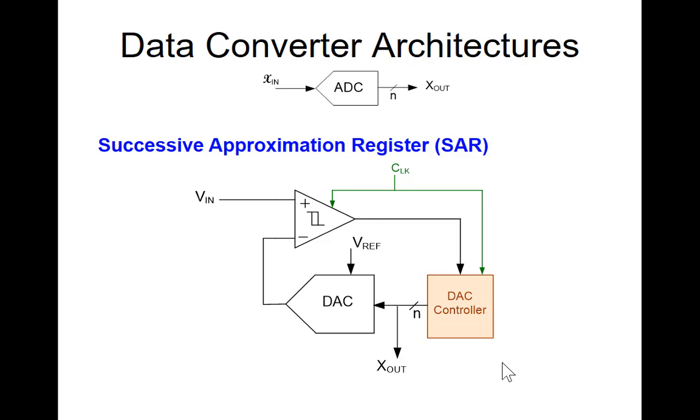Then probably either of those Boolean inputs will be an acceptable output to that ADC. If we had to go through all combinations for a 16-bit ADC, we might have to have 65,000 tests. Oftentimes we'll do a binary search, however, so instead of 65,000 comparisons, we could get by with 16 comparisons and converge to the right code.